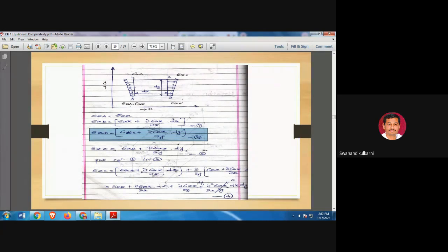Okay, thank you. So now coming to the end part, only one equation is remaining, that is the stress present at point C. At point A, the reference point, that's why sigma xx. For xb, what did we do? We added dou sigma xx upon dou x into dx. Here we only added dou sigma xx upon dou y into dy. So for point D and point B we had taken the reference point as point A. We have considered the reference point as point A.